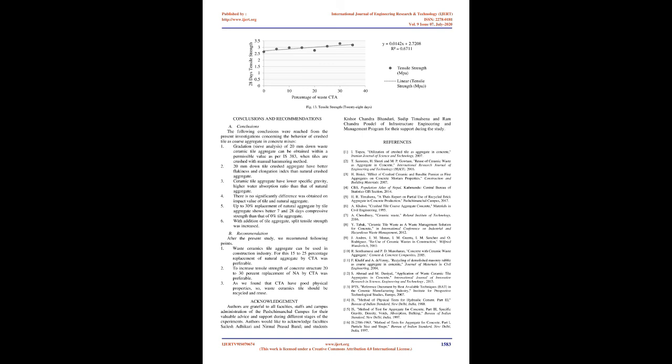Rebound hammer test. At first, 7 days compressive strength of the cubes was tested by rebound hammer. Smith hammer only gives the compressive strength of the surface, whereas the CST machine gives strength of the whole cube material, from core to surface. At the age of 7 days the surface of the cube was soft because of less hardening as well as curing, moist surface. So, the 7 days compressive strength obtained by the Smith rebound hammer is lesser than that of the CST machine. For 28 days age cubes, the surface of the cube was made dry for rebound hammer tests, so the strength given by the Smith hammer was nearly the same as the strength given by the CST machine.